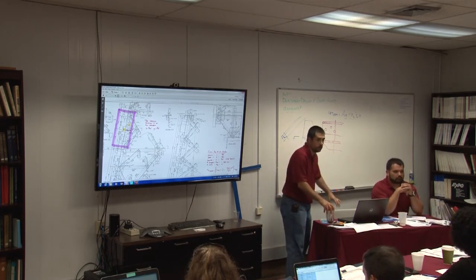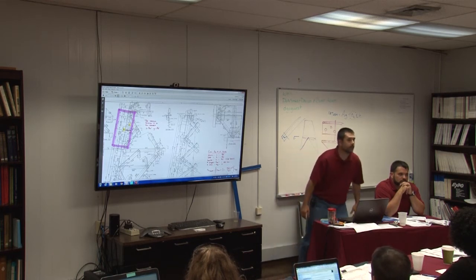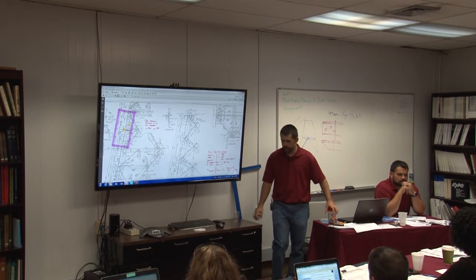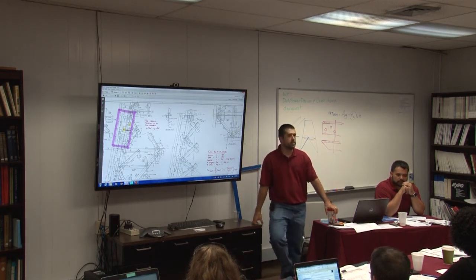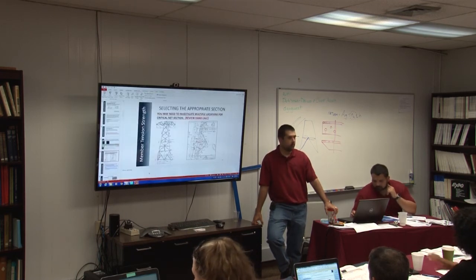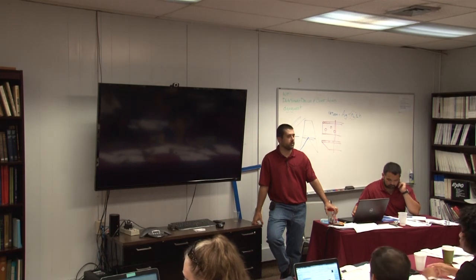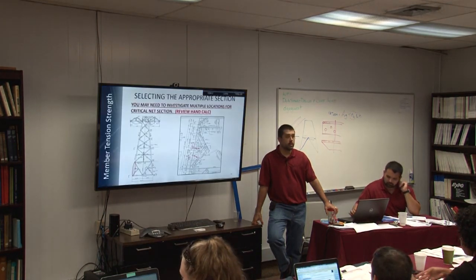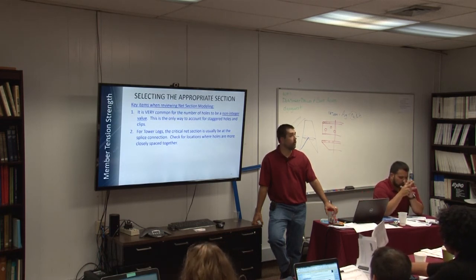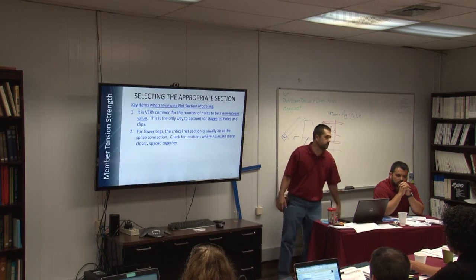I know we included something like that in the substation criteria. Right, like a legacy structure versus new structures. I've recently worked on that. A lot of that decision comes down to: is it a leg member? Is it a critical load carrying diagonal? Is it a tension only diagonal? Are you willing to live with a 5% overstress in a tension only member, especially if you're looking at a wind velocity that's more than code or a 1.5 inch ice or whatever? Those are the decisions that have to be made.